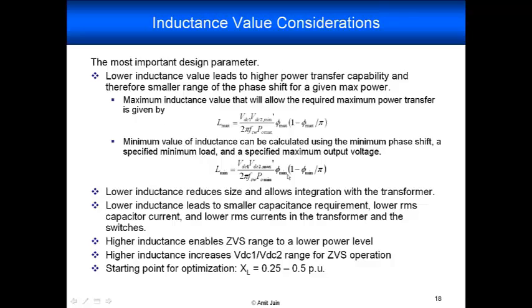So if your resolution is very low, if your resolution is very coarse, then having a small value of inductance will mean that you cannot control the power transfer to a very fine degree. So you want to limit the minimum value of your inductance in that case.